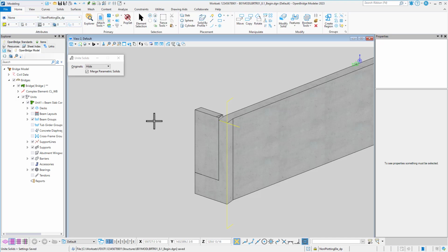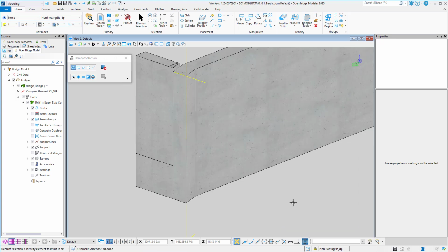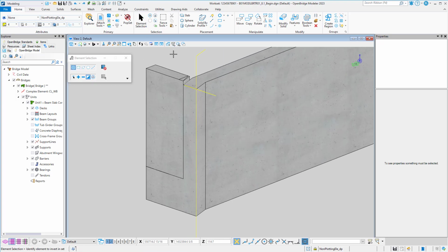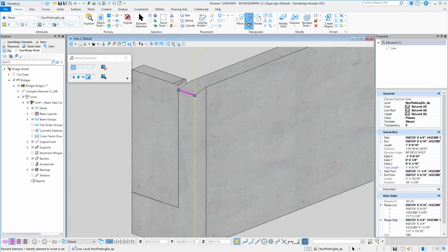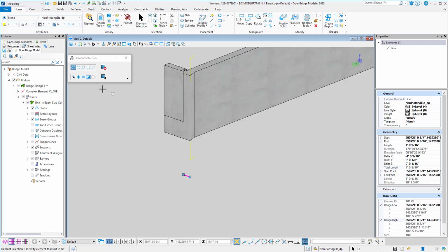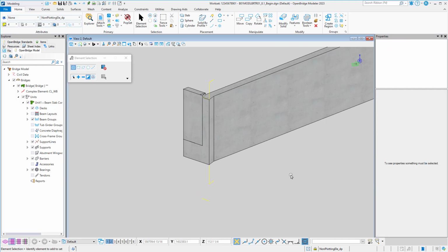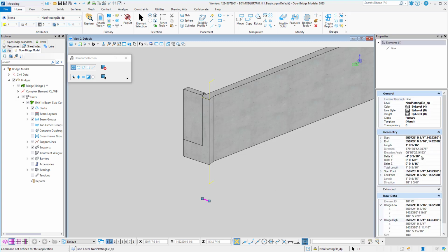The final modifications necessary for the end bent will be the vertical and horizontal lug as necessary for interaction between the end bent and the MSE wall. Let's start with the vertical lug. Let's start by adjusting the shown construction line to match the exact limits of the line it's traced onto, and by making a copy of that line down 15 feet. Let's edit the properties of that new line to have a Z elevation of 105 feet.